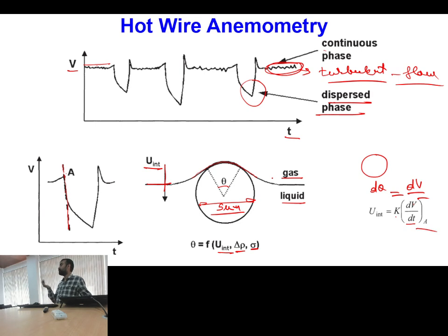It means if you are using, say, boiling or condensation, where one phase is vapor and the second phase is liquid of the same substance, in that type of situation this method does not have good accuracy. It is typically recommended for two component systems. Say if you have an air bubble present in the water, or some kerosene bubble present in the water, then for two component systems, both liquid-liquid as well as gas-liquid, it works well.